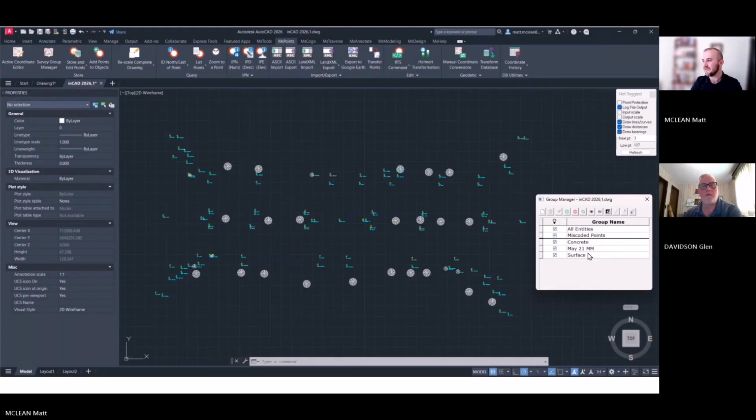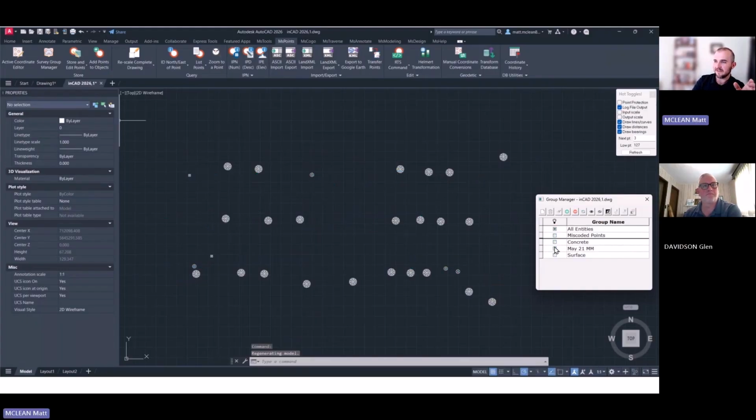So here's sort of the magic of it: I can turn off the field file group and all my points. If I have lines, they'd be in here as well if I was using the Field Genius Sync Wizard importer or the Leica DBX importer.